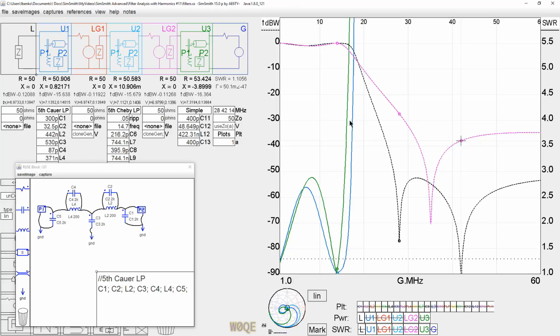It has a higher area where it rolls off than the simple filter did, which is again good. It gives us more tolerance to component variations. It will end up, as you'll see later, having lower inductor currents than this filter had, which is again good. And it has extremely good rejection at the second and third harmonics. So it doesn't matter what kind of a transmitter we put into this. This transmitter can be putting out an absolute square wave, and this circuit would be plenty good enough. It could be doing anything short of having the harmonics be higher than the amplitude of the input.